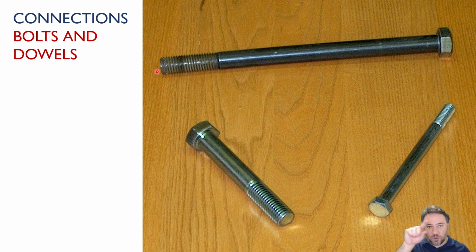That pre-drill hole is typically going to be a little bit bigger than the bolt, and that helps with fit up, obviously. In traditional heavy timber construction, bolts are the way. These days we're going to talk about a lot of different options for heavy timber construction that don't use bolts, but bolts are the classic and still very much popular and in use.